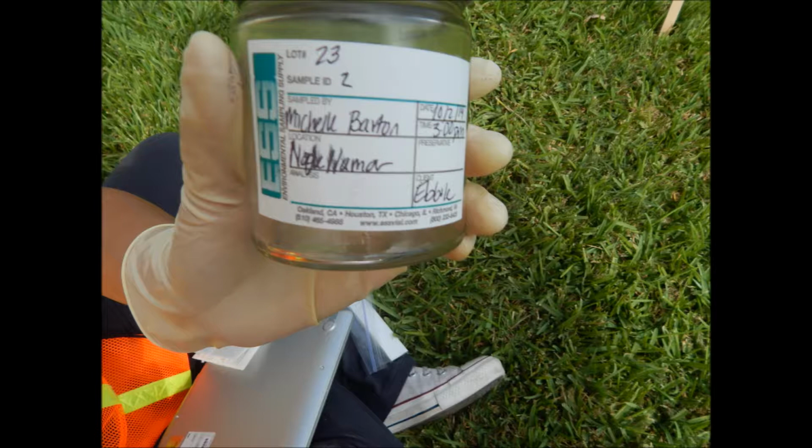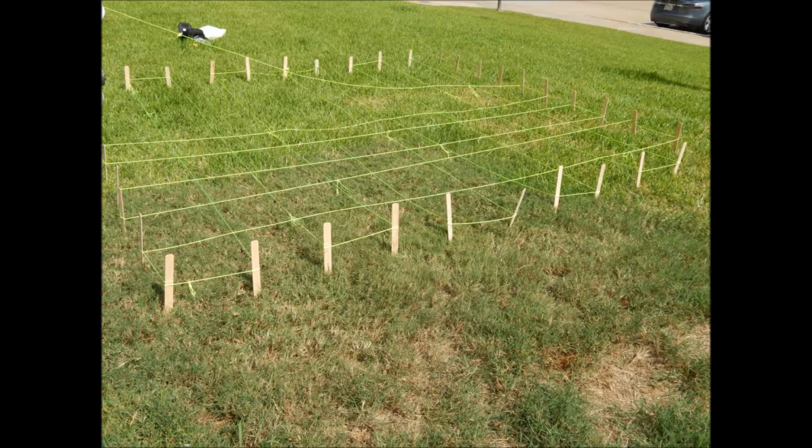Next, label the containers with the lot number, date, location, sample number, and name of the individual who retrieved the sample. This is needed for the chain of custody, which will be addressed later in this video. Ensure the sampling location is appropriate and approved by the client and property owner. All scheduling conflicts should be resolved, and the supervisors should be on location when samples are retrieved.